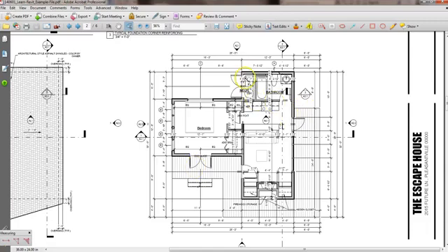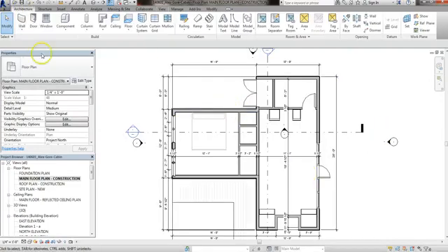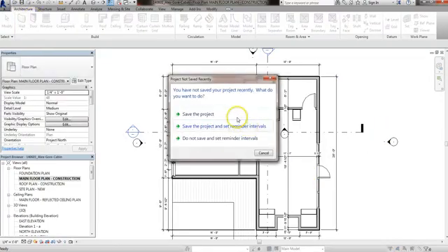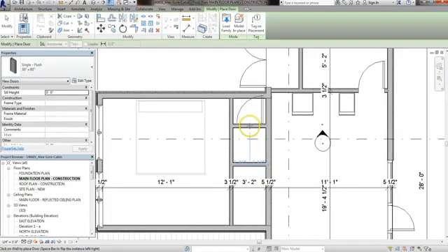So go ahead and put in all your components like this. One thing I forgot to show you, when you put in all your dimensions, is this little equal sign. So let's put in a door right there and show how that works. We don't need to save it. So let's hit spacebar.